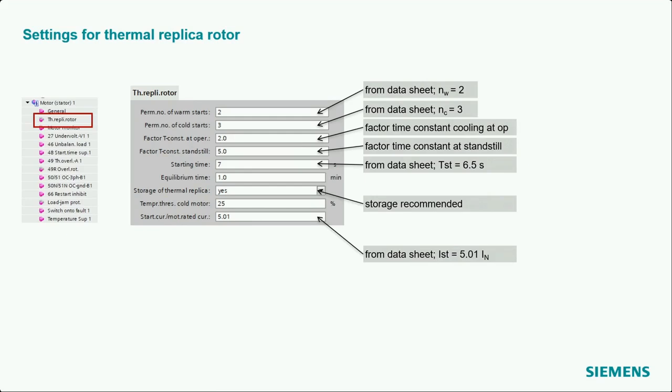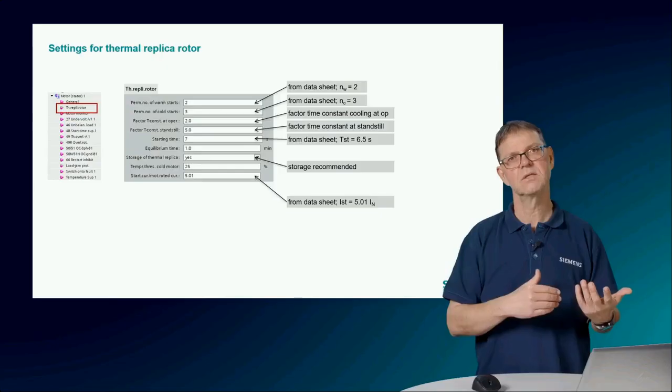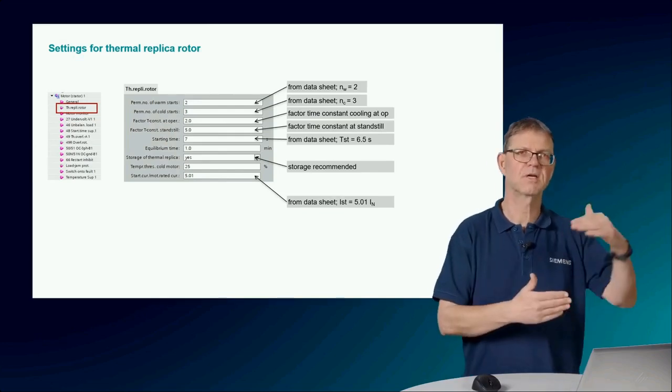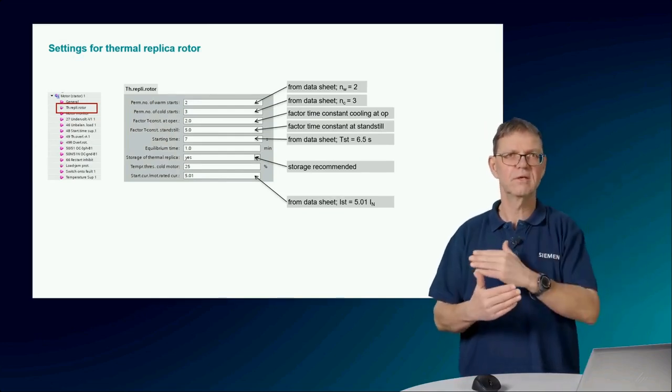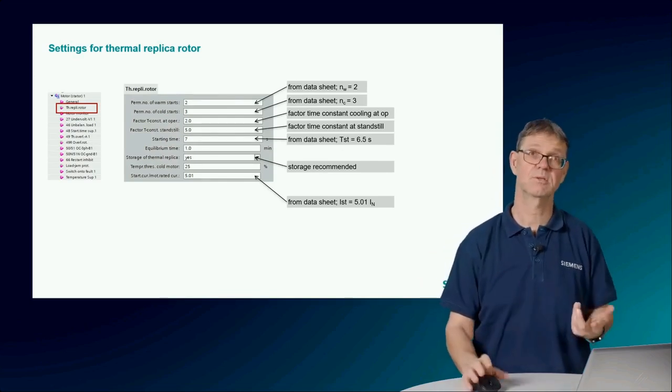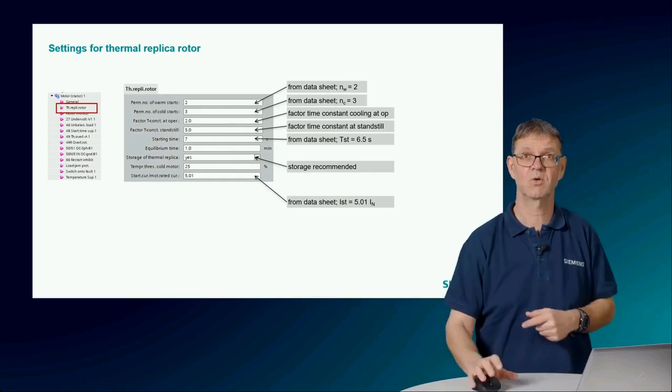So for this we have the second factor, T constant standstill, and we have another one built in. This is for calculating the temperature when it goes down, when the actual current is lower than before. So we have a possibility again to be more on the safe side, to go down more slowly than going up, with a time constant. So we can also extend the time constant.